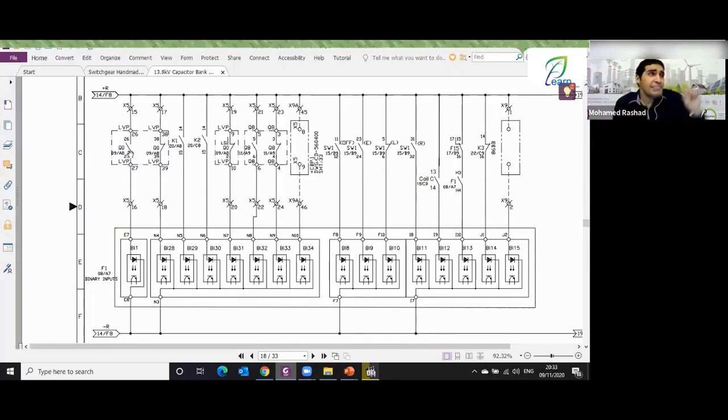I can send this information to the people sitting in the SAS or in the SCADA, and there they can program it. If this first piece of information that is present here is received by the relay, it writes a text saying what this information means, for example, spring not charged. So this information must truly come from the source of spring not charged. How does this happen? You connect a negative to the binary input.